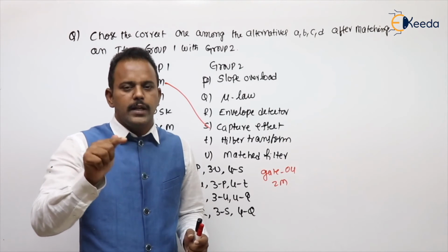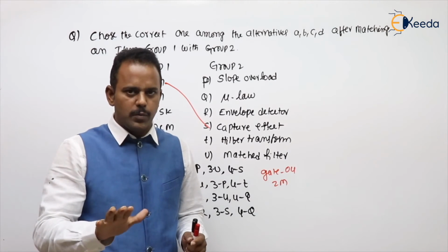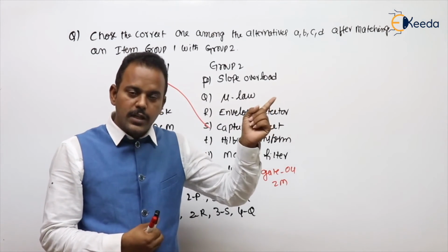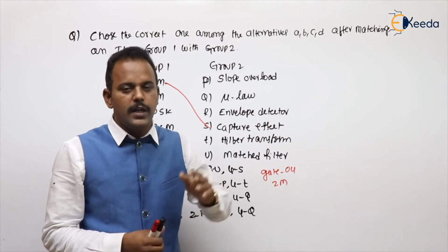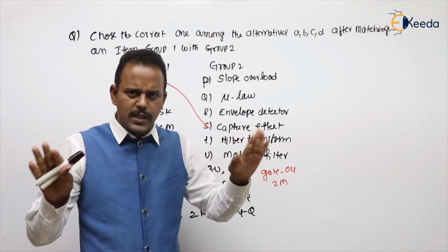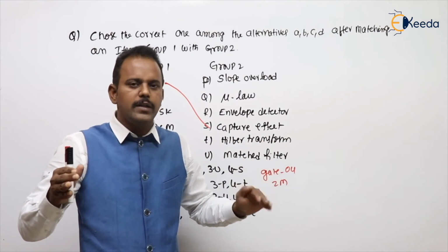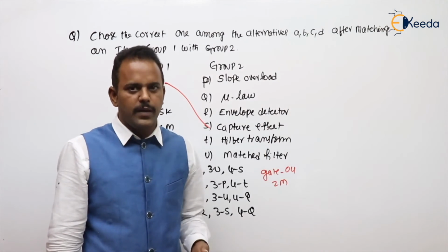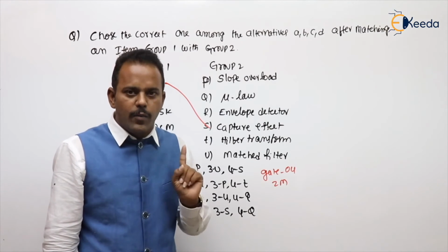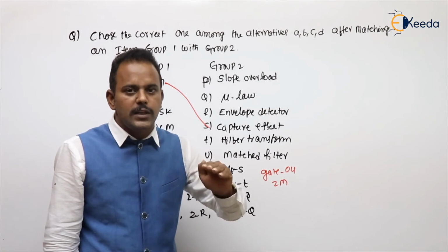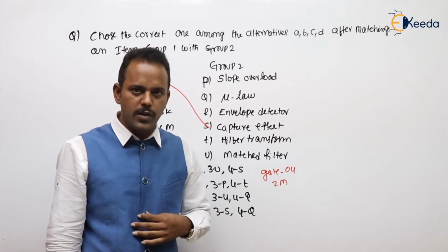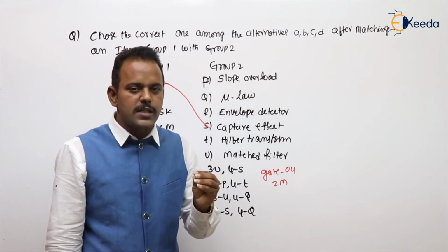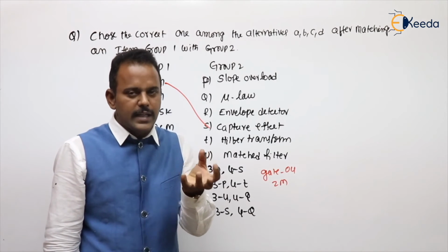The Hyderabad station of 93.5 is available here with more strength, and another station from an adjacent city is also at 93.5. Both are the same frequency. One is from Hyderabad, another from another city. If both are available, FM will always capture the stronger one. If 2 stations of the same frequency are available, it always captures the stronger one. That is the capture effect.